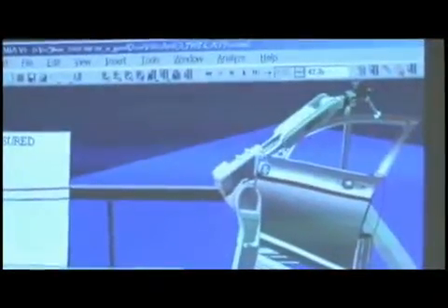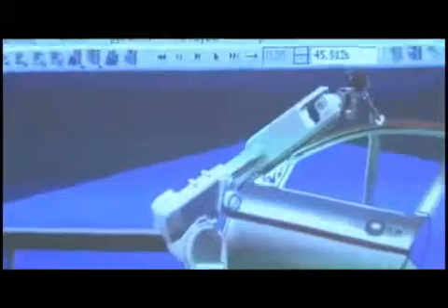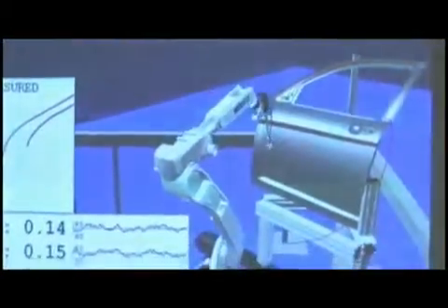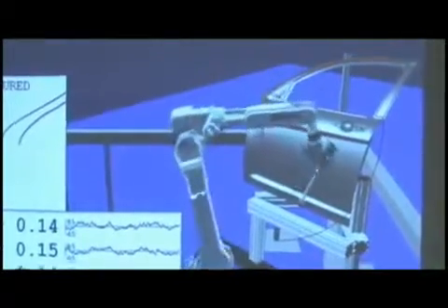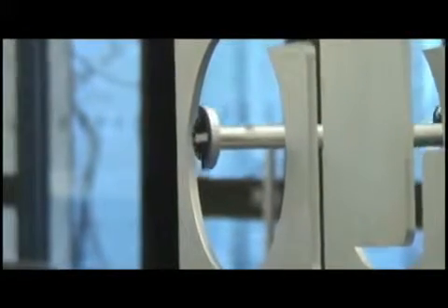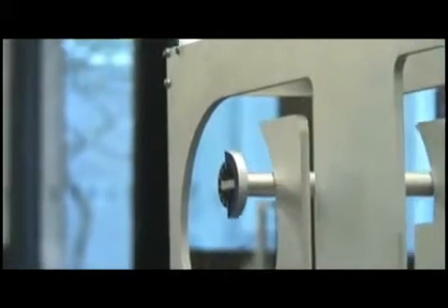The compensation phase takes the program that is generated offline using the nominal data and then corrects that program to compensate for all the actual errors that we measured during the identification phase. When we complete the compensation phase, we take the brand new robot program and we download that to the actual robot controller. And then that corrected program is what's run.